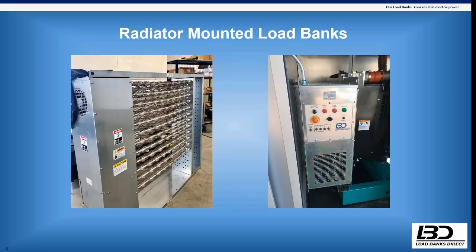But if you need more watts, you need more heat, you need more resistors. So if you tried to put 1,000 kW, a megawatt worth of resistors, on the tail end of a radiator that's cooling a 1,000 horsepower or 1,000 kW engine, you're probably going to overheat something in the system. And also, you're adding so many resistors at that point that you're probably exceeding the static pressure rating of the radiator fan. So we found in our experience 30 to 50% is a really good number to work with. We can go a little bit higher. We just need to know them on a case-by-case basis.